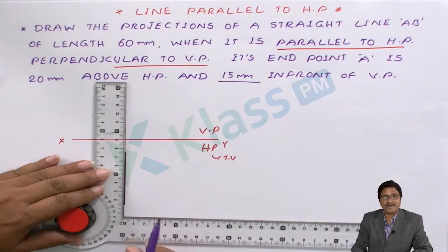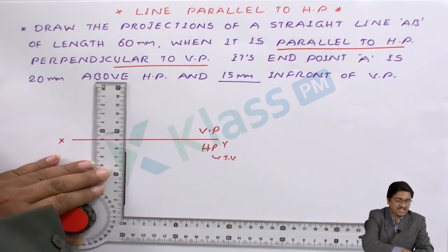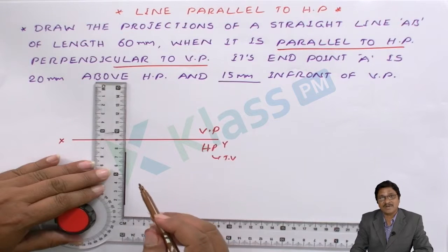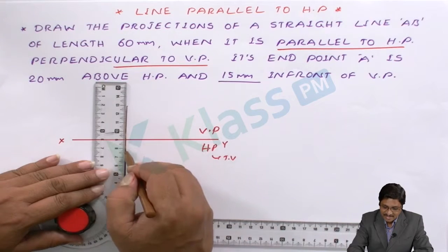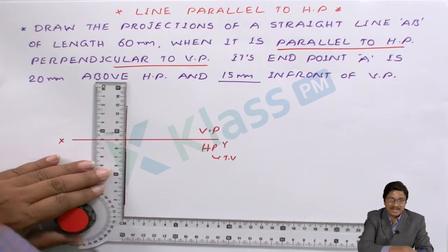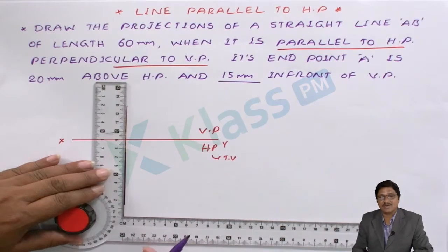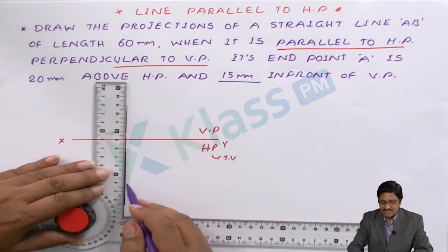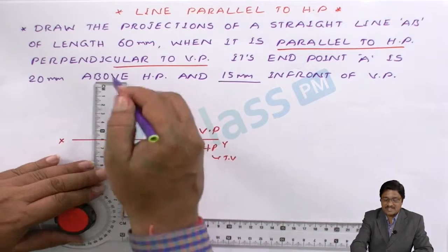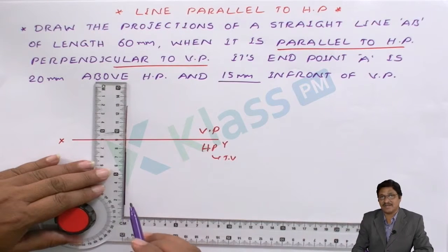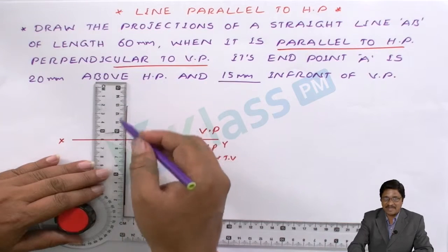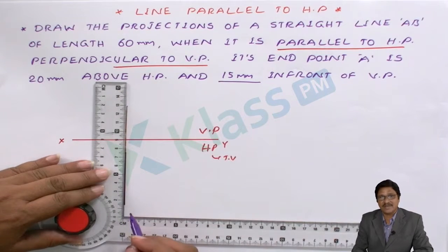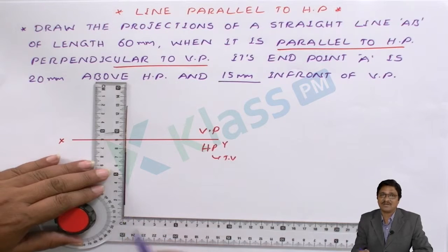So this is the front view; the front view is to be drawn. Why? Because once you have the top view, we know the fundamental concept that the front view and top view are always in the same vertical line. By taking a 2H pencil, draw a light line so that you can align along it. The pencil is to be used differently: the solution is to be drawn with HB, while this reference line is drawn very light, only for the sake of adjustment.